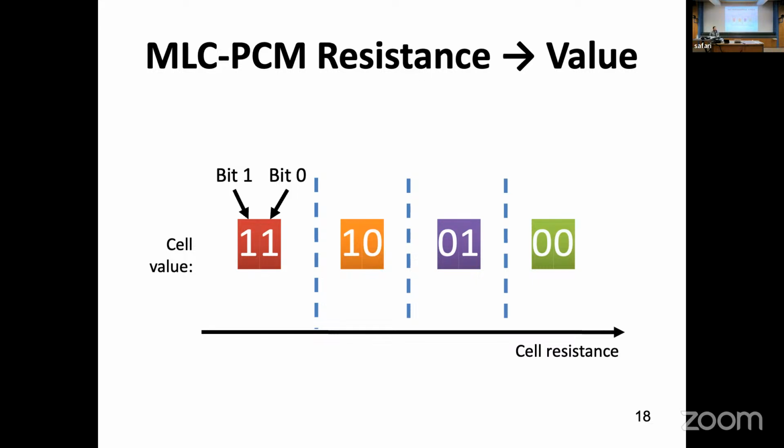Is this a limitation on how much? Yeah, it's a really good question. So the major disadvantage of this kind of non-volatile memory, the big problem, is the endurance problem. That means that when you frequently change the status between different phases, sometimes it cannot be changed anymore. For example, at the beginning, the range of the resistance you can change is this large, but when you write it very often, the range will shrink, until one point where it cannot be changed anymore. So there are reliability issues with the endurance problem in NVM, and it's a very big challenge when you're using NVM. I will talk about more details about this later.